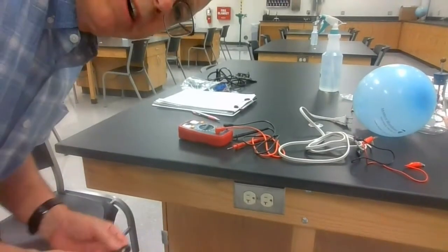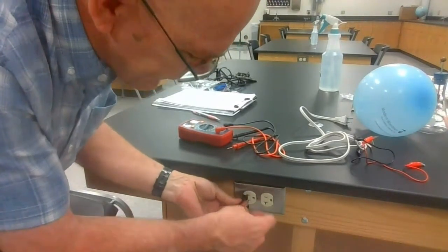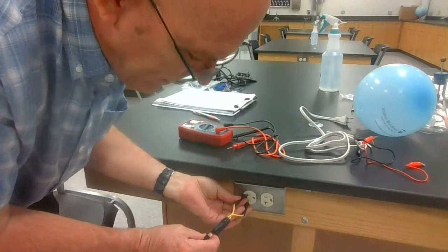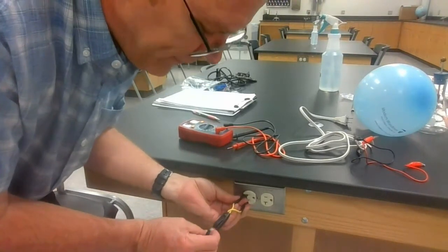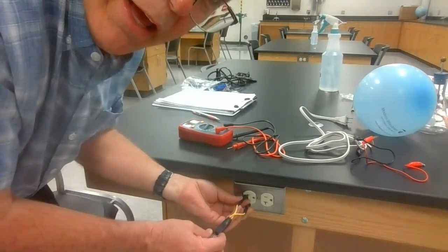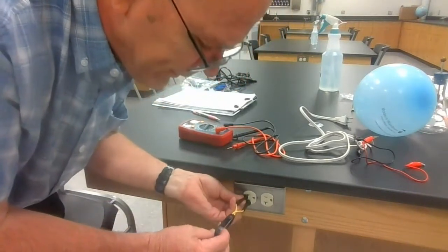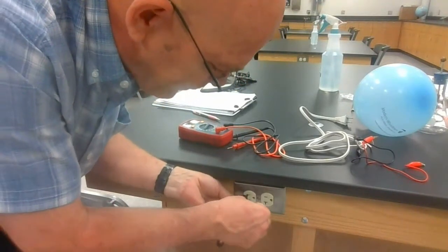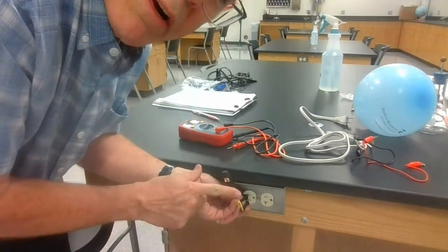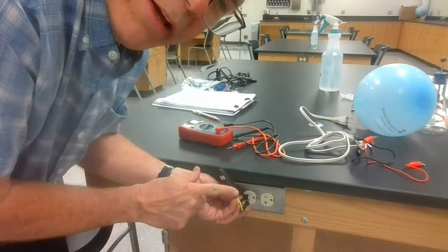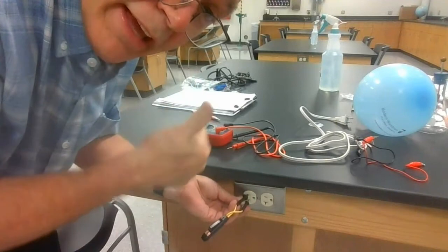Basically, we can use these to test to see if there's a good circuit in here. If I stick them in here, it should turn the light on. I don't know if you can see that very well or not. If it does, then that means yes, it is a complete circuit and it's good to go. If I plug something in here and it doesn't work, I can stick this in here and find out if the reason is because the circuit's messed up. If the circuit's messed up, I need to go in there and rewire it or something. If it turns a bright color, then I know that the circuit is okay. There must be something wrong maybe with my appliance or something like that. But this part is A-okay.